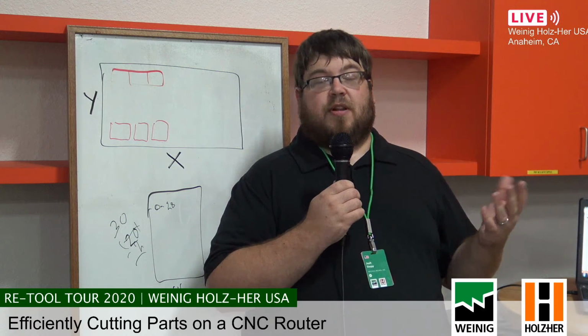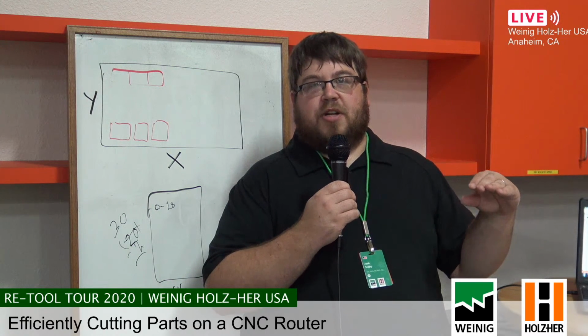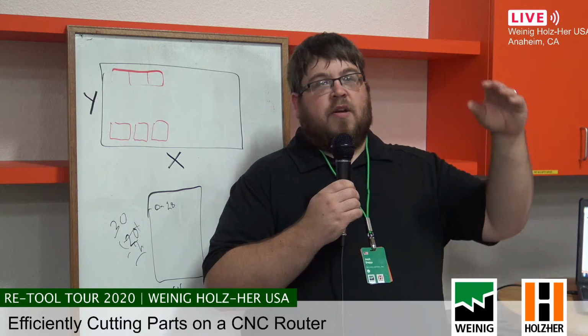It's going to be 24 inches wide, 12 inches deep, made out of 3/4 inch white melamine. So all those are options. The minute something changes, because everything's done parametrically, we know how, if we always wanted to bore 1/4 of an inch into the material and we go from 3/4 to 5/8, we know how that changes based on parametrics.